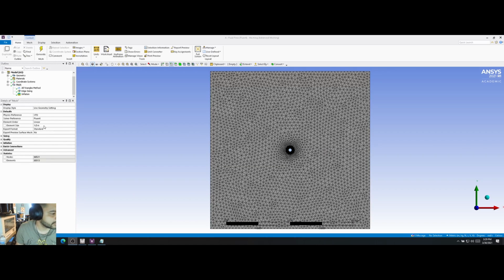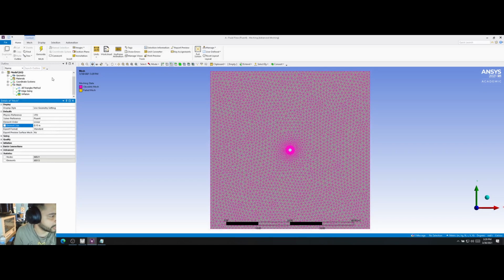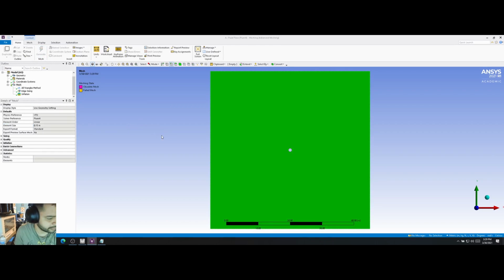So since we got that, we're gonna define that as 0.15. So our mesh is gonna be finer, and we're gonna have better results. So we're gonna select that, and then now we're just gonna generate. And now we're just gonna continue once that's done.